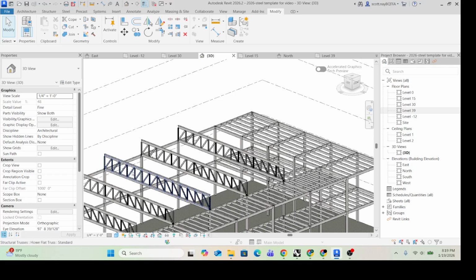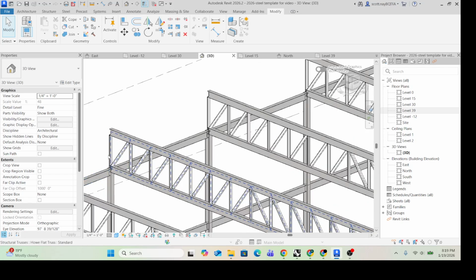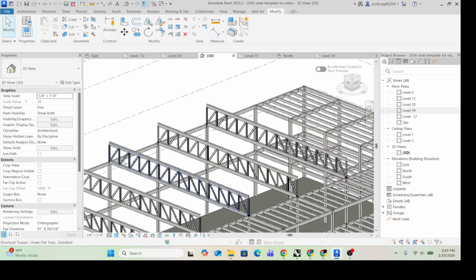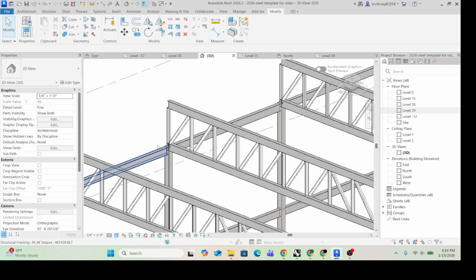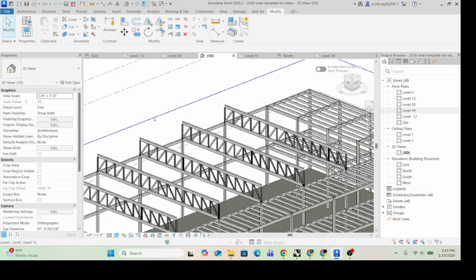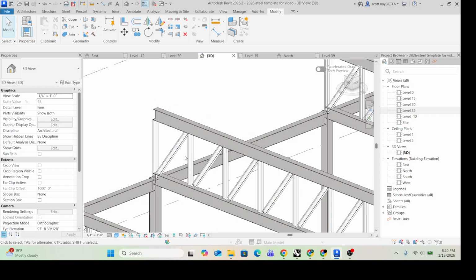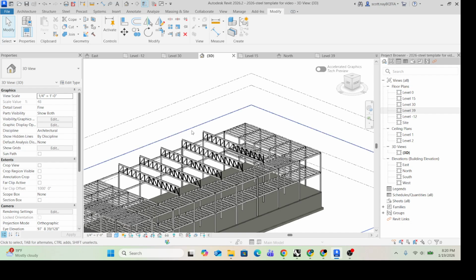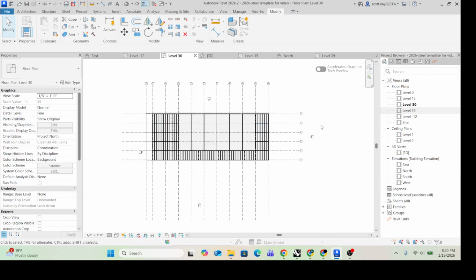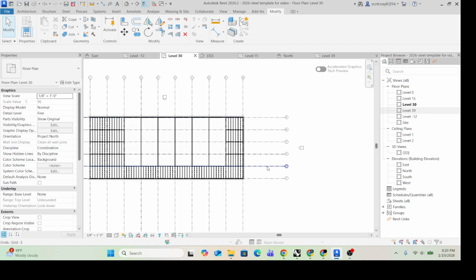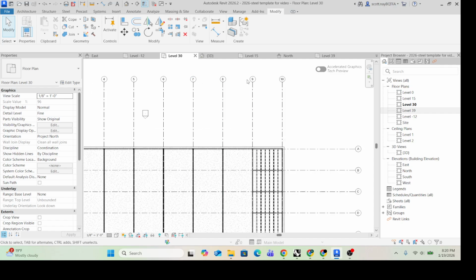Now we've each got different scaling, so we're each going to have a different number of verticals. I'm going to count mine so that I know how many I need. And I've got 15. So after I make my first one, I need to use an array to space them out because we want the load of the roof to go from the curved piece straight down this vertical. So I'm going to come to my north elevation, but first I'm going to double check.